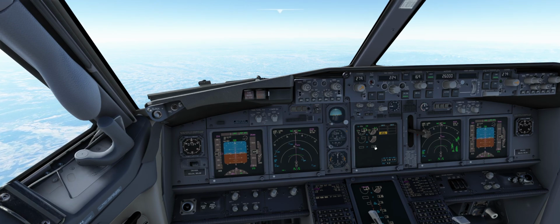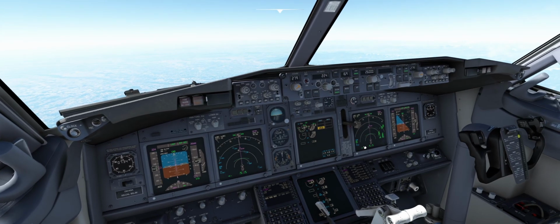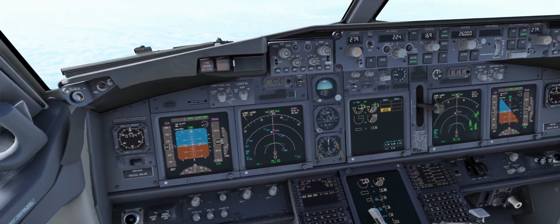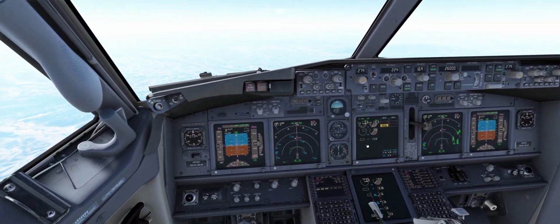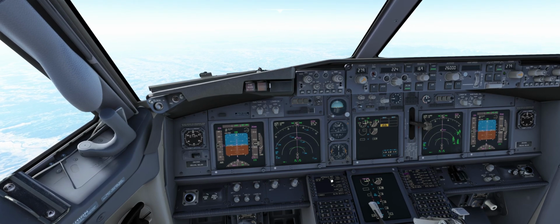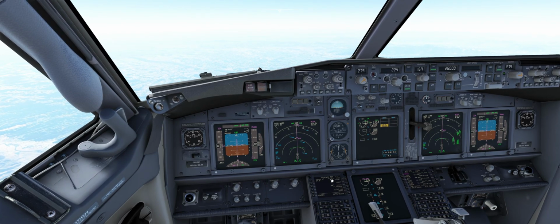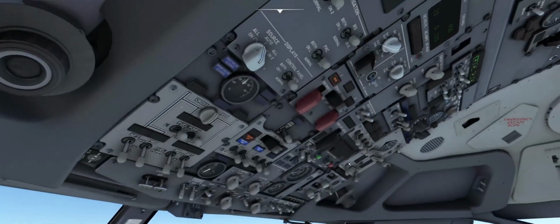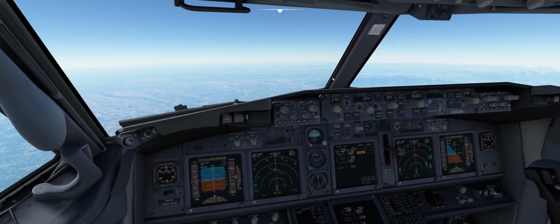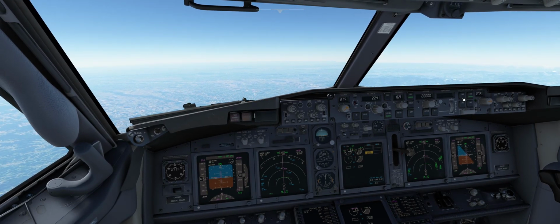Okay, I think so far it was understood. And what we are going to do, flap inhibit, because while landing with one engine inoperative we are using only flaps 15. So in your init page, the flaps 15 are used while landing in two cases. The first case is one engine inoperative, and the second case is if you completely lose your hydraulic system B. Okay, now we have APU available, so we can put APU on bus, and now if you would like, you can change your autopilot B to autopilot A.